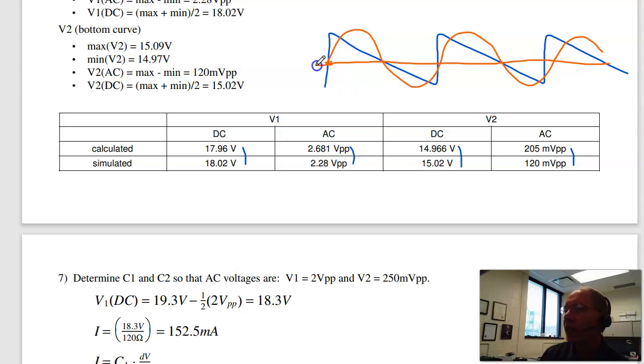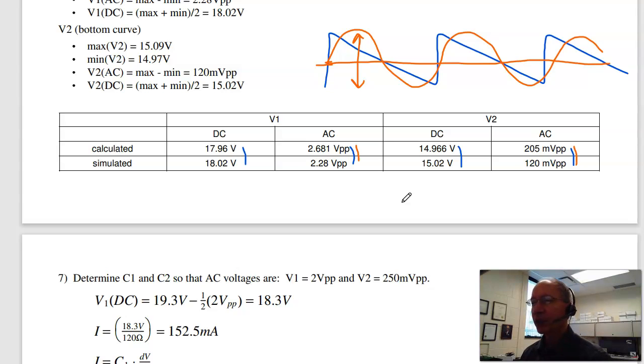of the old problem. I keep the same DC voltage, keep the same AC voltage peak to peak, keep the same frequency. So if I pretend the blue line is a 60 Hertz sine wave with the same peak to peak voltage, same frequency, same DC, almost the same problem. It's not the same problem. It's a little bit different. So likewise, these answers will be a little bit different. But it gets you close. If you want to get closer, I need to use Fourier transforms. That's the topic we'll be covering later. It's also covered in Signals and Systems, or use Circuit Lab.